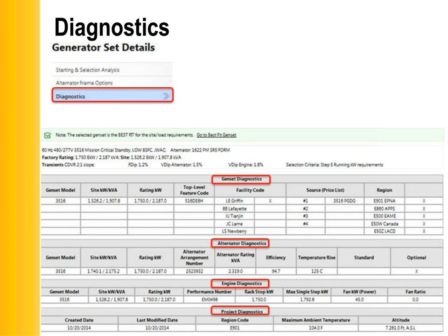Here's another one. Are there other places that I can get and compare technical data in the SpecSizer tool? Another good question, Mary, from the audience. Yeah, there is. I actually covered this in 101, but it's noteworthy to mention. We talked about when you're creating a genset sizing, you start out defining your site conditions on that page. You add and sequence your loads on the add loads page. You size your genset on the select genset page. You can also go to generator set details and see a lot of good technical information data.